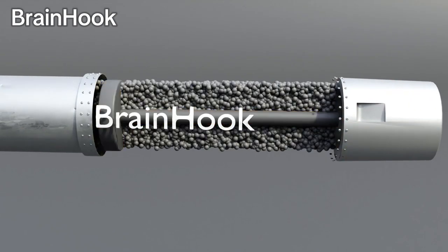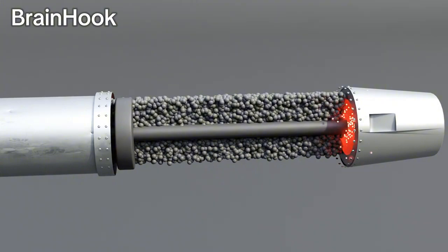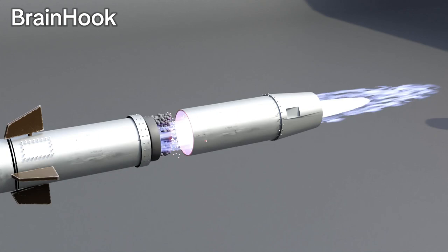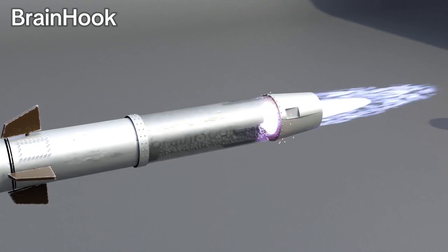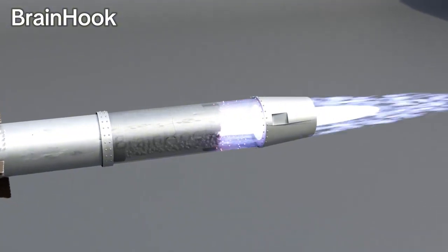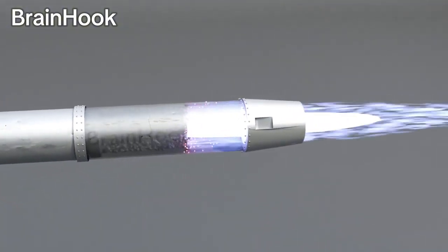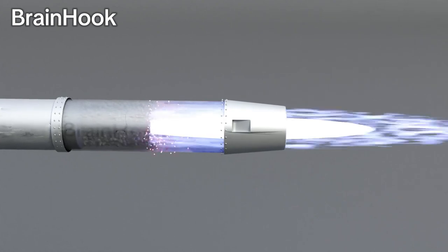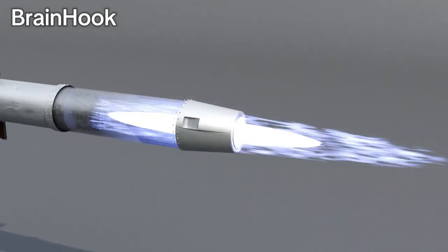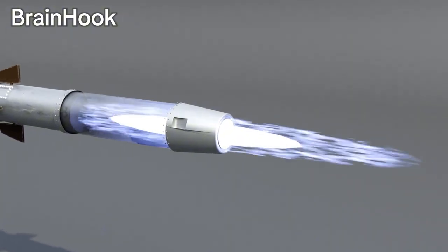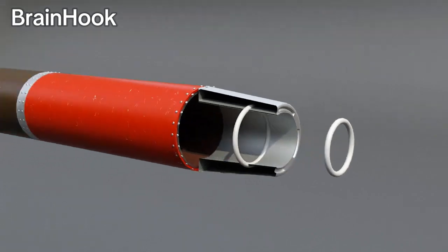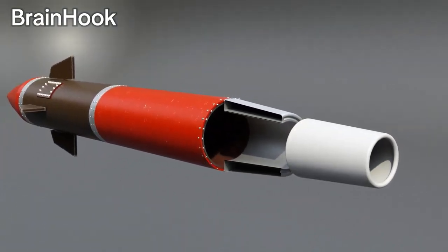This is electrical ignition. When it is ignited, the combustion process begins in the propellant. The propellant mixture is housed inside a strong case known as the motor case. This motor case plays an important role because it acts as a very powerful pressure vessel. Inside it, solid fuel and oxidizer react and complete the combustion process. When the propellant starts burning, high-temperature combustion gases are produced. The produced gas flows through the nozzle. This nozzle is designed to accelerate the gas flow. The rocket's propulsion system comes to life when the combustion gas flows through the nozzle.